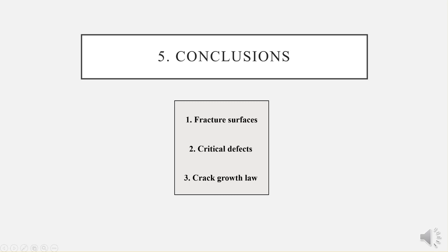Furthermore, we came to the conclusion that assuming all the defects to be crack-like was a useful approximation. Finally, fatigue crack evolution was correlated to the observed fracture surfaces, and one of its regions, a very bright one, was matched with the shape of the numerically simulated crack during its transition from an embedded to a superficial situation.